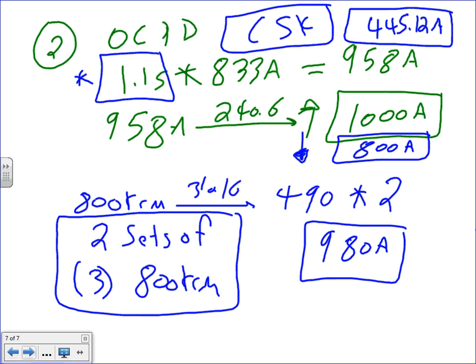Why did I multiply by 2? Because I paralleled 2 sets. If I paralleled 3 sets, it would be multiplied by 3. But I need to test whether the overcurrent protection device is capable of protecting my conductors. In this case, no, so I went down. You can go down or up, no problem. If I don't want to go down to 800 amps, I could have gone higher. The next size is 900, so I would go for 2 sets at 900.